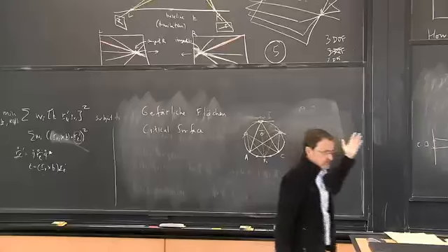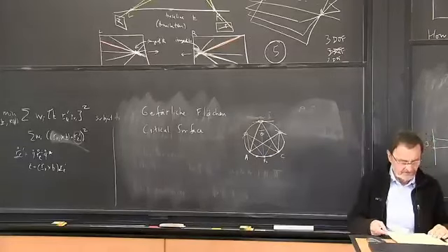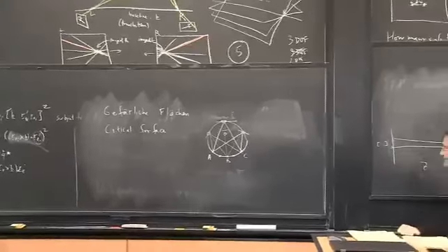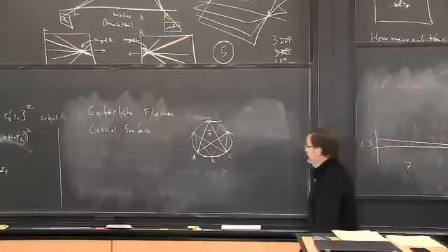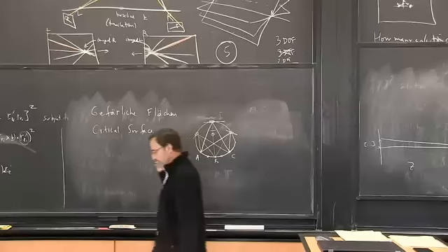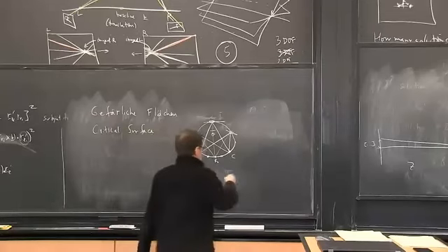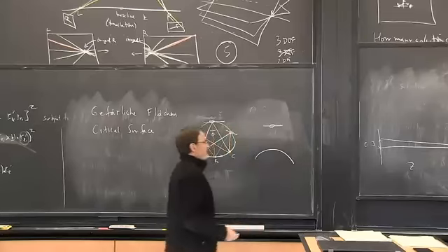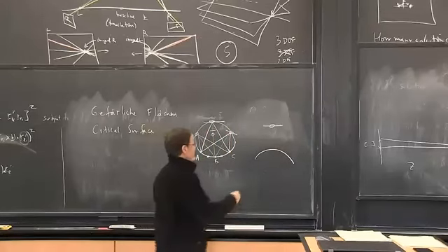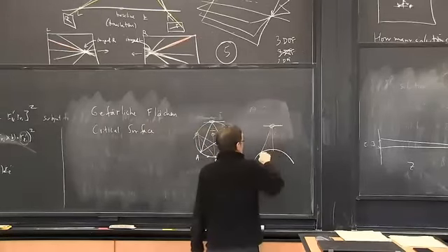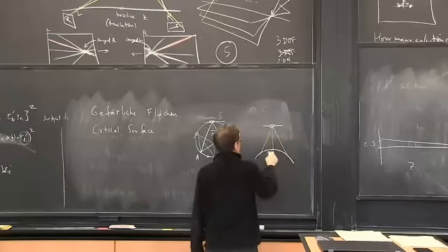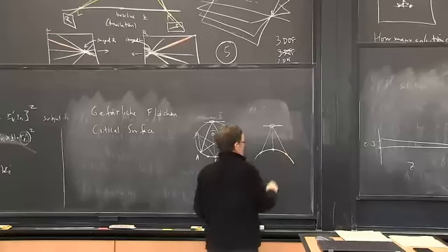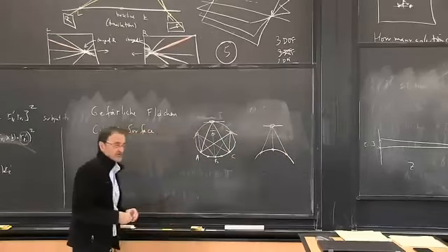Now this is a cross-section, this is 2D, so this isn't the whole story, but it gives you a plausible way of understanding why there might be a problem. And this is why when they lay out the flight plans for mapping, they never do that. They prefer to do this. Fly the plane over a ridge rather than over a valley. Because here, when you move over, the angles between different images of different surface features do change a lot.